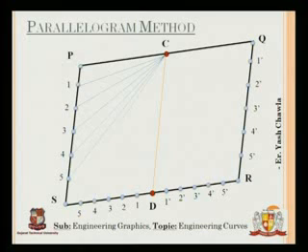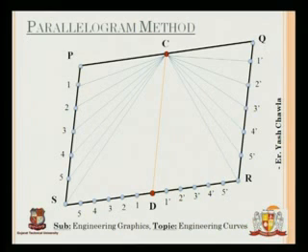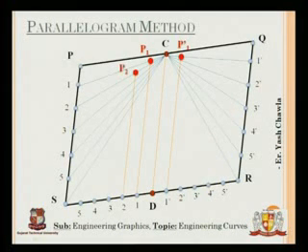Again these lines are drawn: C, C1, C2, C3, C4, C5, C6, C7, and on the right hand side C1 dash, C2 dash, C3 dash, C4 dash, C5 dash, and finally C6 dash. Now these are the points. Now this is C1 again, so I'm going to join 1 by a vertical line to C1 and mark the intersection point as P1. Let's see, this is my P1. On the right hand side, if I do it, it is P1 dash.